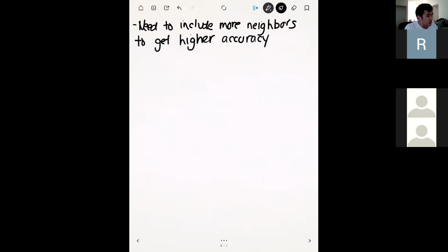So if you look into the literature, even for finite difference, there are tons and tons of different ways that you can achieve higher accuracy by involving more neighbors. The literature goes very, very deep on this. So we're going to go over just one scheme that's really popular. It's called the QUICK scheme, and it's actually an acronym. Right? So I'm going to draw this out here.